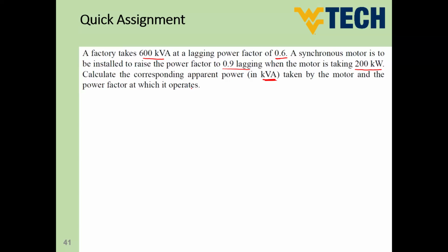I mean, you don't need to use the relation of the excitation with the terminal volt, the armature current and the synchronous reactance. All of that, you don't need it here. So you will solve this question as if you have a capacitive load, improving the power factor of your system. Okay, why am I saying capacitive load? Because it's not only a capacitor, it's an RC load. Why RC? Because it absorbs a certain amount of power.